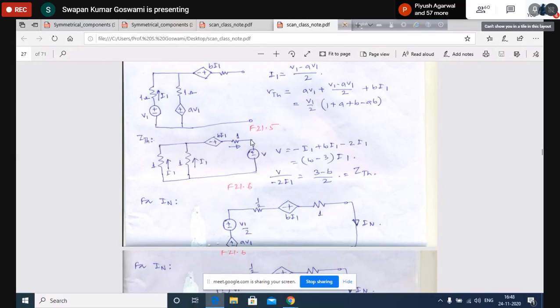here we shall have to measure the impedance. How? As a ratio of voltage and current. Why do you have to measure the impedance here, particularly in this case? Because we have some dependent source. And the Thevenin impedance or Norton impedance, whatever impedance you will be determining, has to be done by removing the independent source but retaining the dependent source in the circuit. That means the dependent source must be allowed to operate.